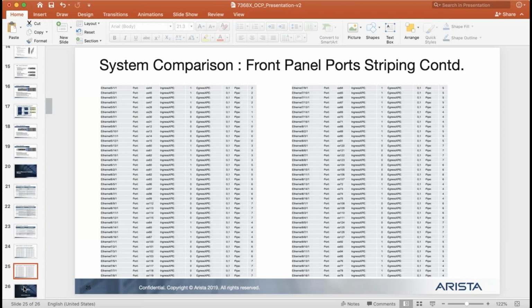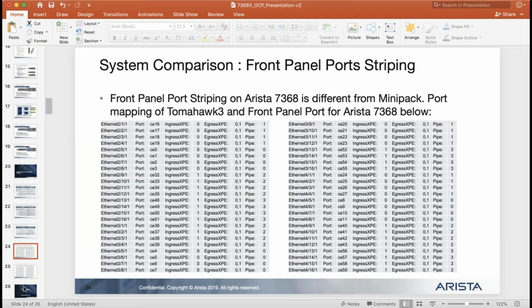Is the buffer in the Tomahawk segmented into separate forwarding processors, or is it a unified buffer? The forwarding is one single system. The buffer is divided into two ITMs, and it is divided into 32 megabytes of buffer. Depending upon the ports, a given port can be part of a given ITM, and so it would have access theoretically to the 32 megabytes. In addition, that 32 megabytes is divided into a quad. Depending upon the given ingress pipe and egress pipe, the buffer will further get split in that 32 megabytes. So from a forwarding perspective, it's all a single chip, but from a buffer perspective, it's divided into ITMs, divided by 2 basically, and further down divided by ingress pipe and egress pipe, which is divided by 4 at that point.